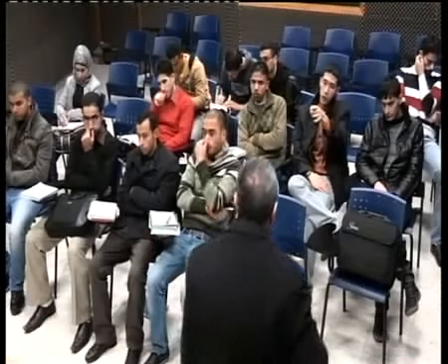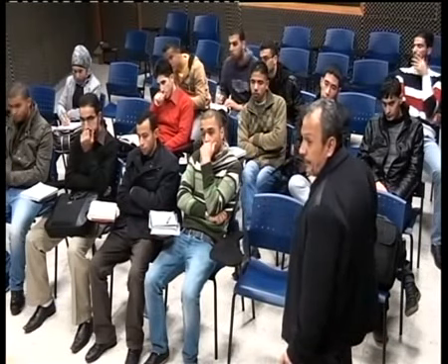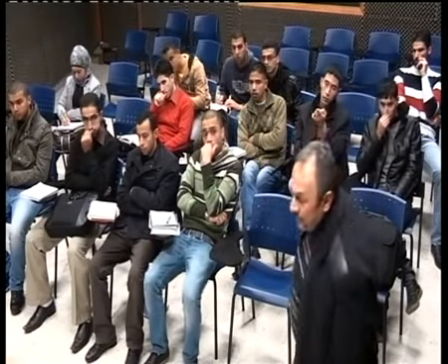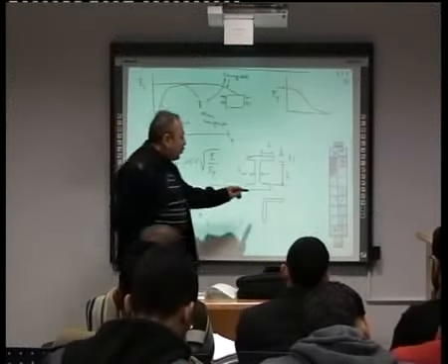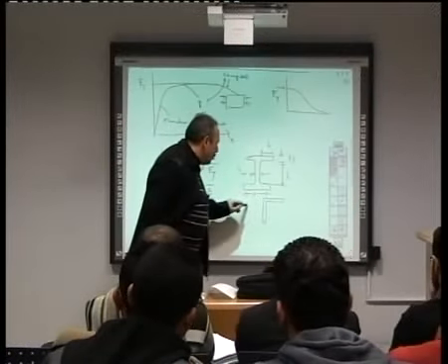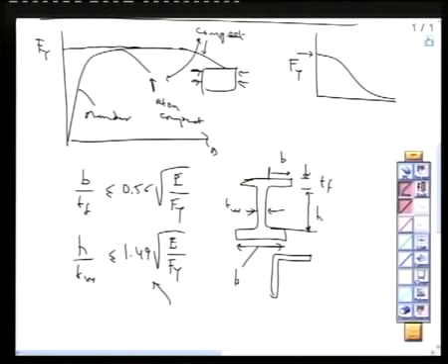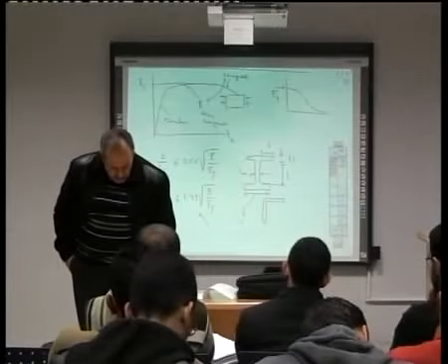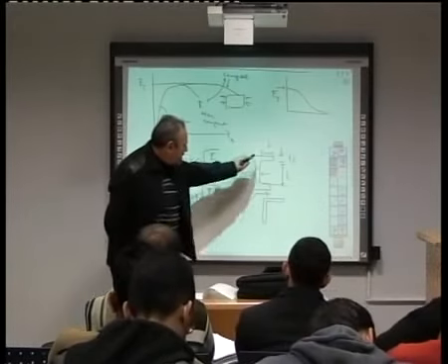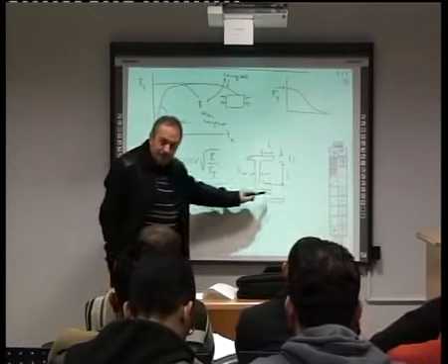That equation, b is divided by 2tf, not by tf. Now listen, if I am thinking of b to be this total, then you are right. But if I am thinking of this to be only b, then this is the equation. So make sure, what do you mean by b? If you mean b the total flange width, then you are right. If you mean by b what I wrote on the blackboard, then I am right. And both are speaking about only one item, because you know that this is almost 1/2 the total b.